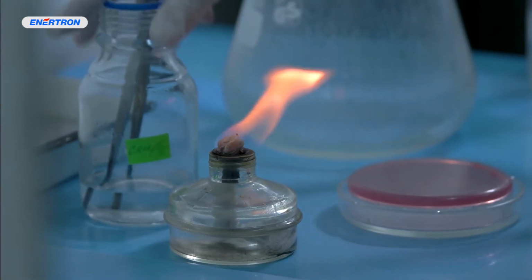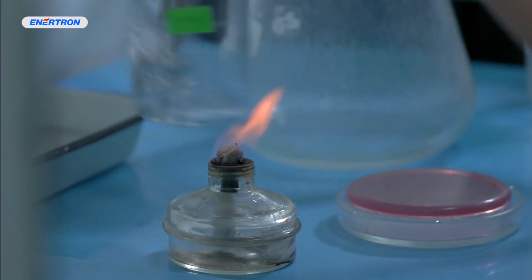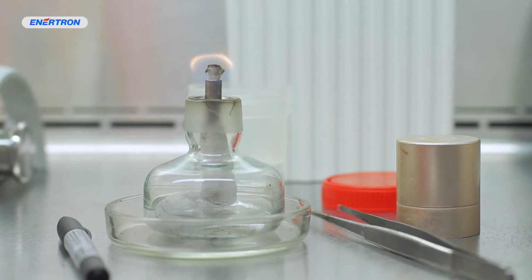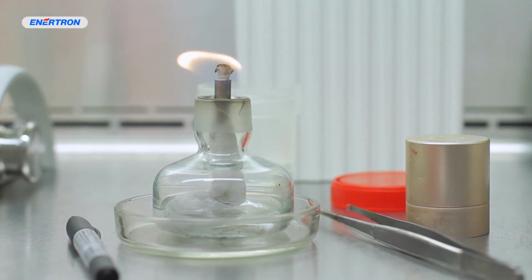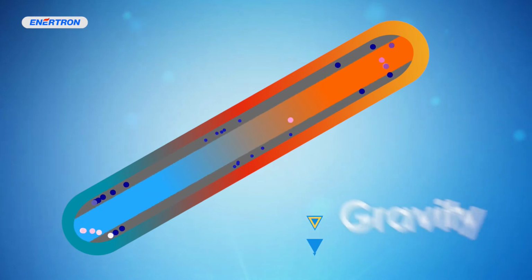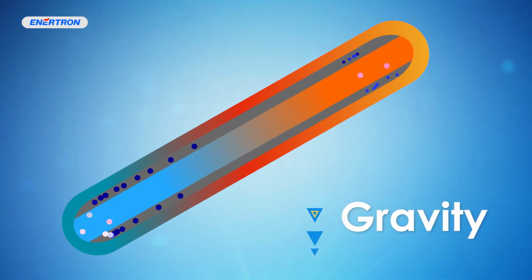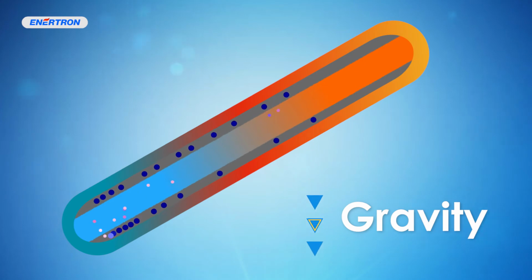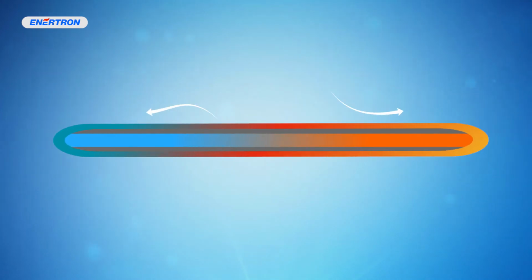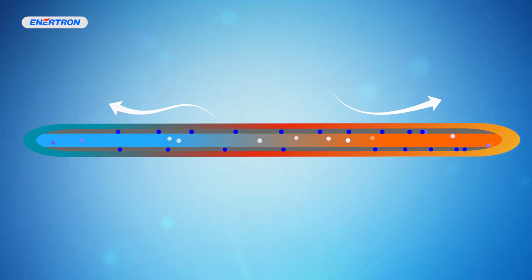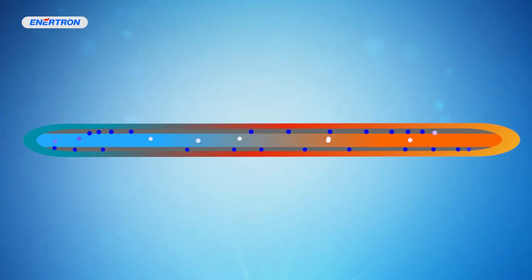In a real-world application illustrating capillary action, you can picture the alcohol inside of a lantern as it propagates up against gravity, or a sponge as it absorbs water on a floor. A heat pipe would not be able to function at an against gravity orientation where the capillary action is not strong enough to move the condensed liquid from the condenser back to the evaporator. Or, in the case of a long heat pipe application, where the capillary action is not strong enough to propagate the liquid within the wick back to the evaporator. This is capillary limit.